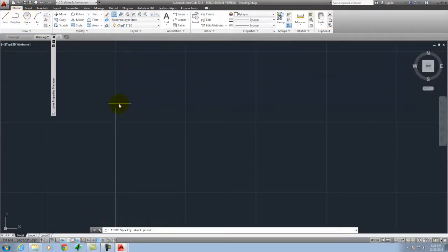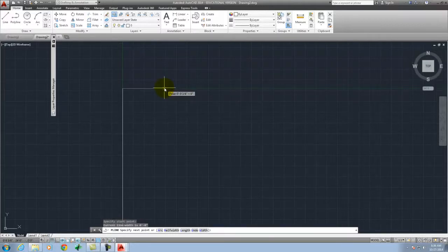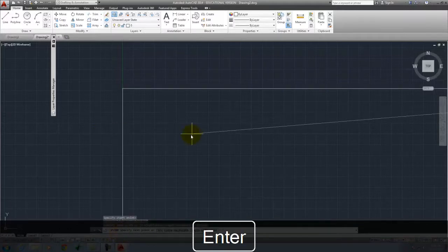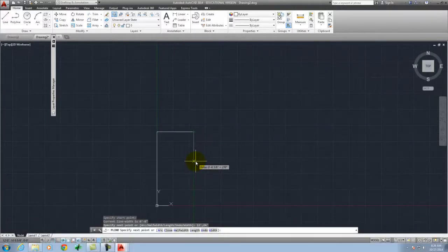I'm going to go to polyline. I'm going to click on the end. It's going to give me that little green square. And I'm going to draw my next coordinate. In this instance, my next coordinate, because these two options are off, I'm going to type in, let's see if I remember here, 12 feet, 24 feet. This is what's called an absolute coordinate, which basically is saying in the general XY plane, if this is point 0, this is point 0, 24 feet, this point is 12 feet, 24 feet in absolute coordinates.